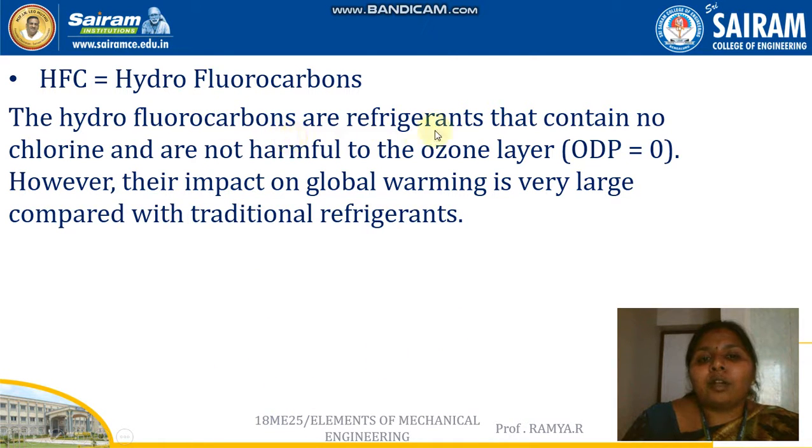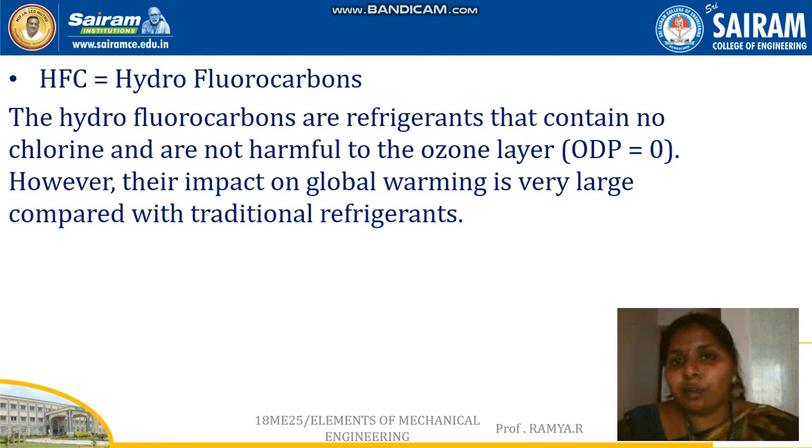The next one is the most important refrigerant, hydrofluorocarbon. Hydrofluorocarbons are refrigerants that contain no chlorine and are not harmful to the ozone layer. So the ozone depletion level is 0. However, their impact on global warming is very large compared to that of the traditional refrigerants. There are some other refrigerants also, like Freon. In Freon there are two types, Freon 12 and Freon 22.